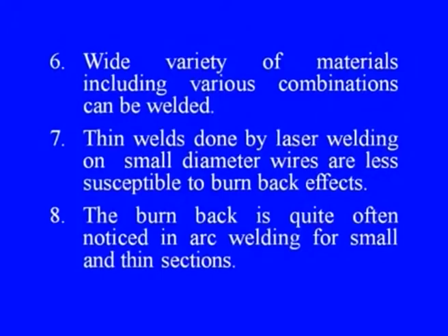A wide variety of materials, including various combinations, can be welded by the laser beam welding method. Thin welds done by laser welding or small diameter wires are less susceptible to burn back effects. This is clearly an advantage. Burn back is quite often noticed in arc welding for small and thin sections, which can be easily avoided in the case of a laser welding system.